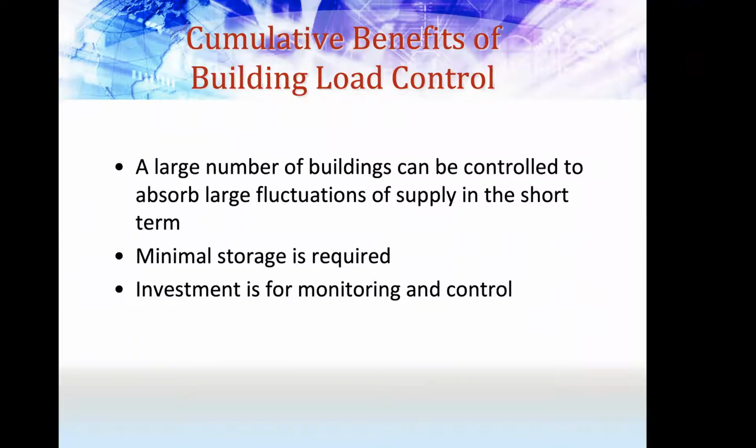When the rooftop solar is fluctuating, because I depend on that solar for my academic building operation, I can go there, remotely control some hallway lighting, corridor lighting, classroom lighting, change the thermostat setting, and manage that. If I did that, I still need some storage, but not as much as if I did not play with the load, as I just said.